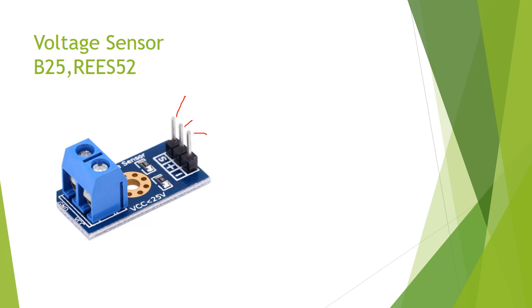Okay, the signal can be measured now. This is your input signal, and 25 volt is the VCC voltage. This is the VCC terminal, and this is the ground terminal. So you can measure up to 25 volts. The voltage must be not more than 25 volt. Okay, 25 volt is also quite a large voltage if you are dealing with the electronics part. So this is the level.